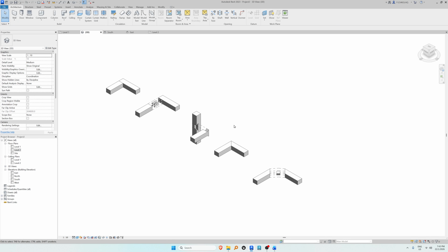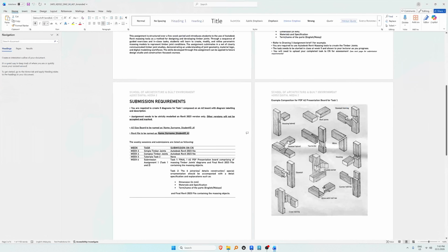Right, so you should have your exploded diagrams. So there's 1, 2, 3, 4, 5. And I want you to make the half mitre with lap. Okay, so you make that one by yourself and figure it out. Right, so the mitre angle, the top one would be the same as this mitre, so 45, and then it's half mitre. If you think you can take this mitre that we created and edit it, it'll be faster. But if you cannot figure it out, try to make it from scratch.